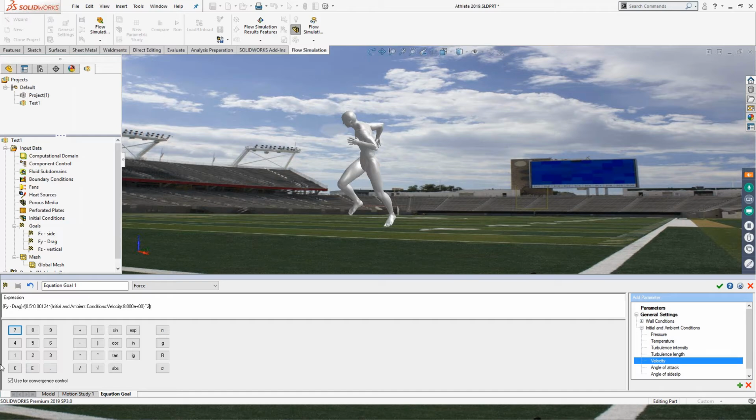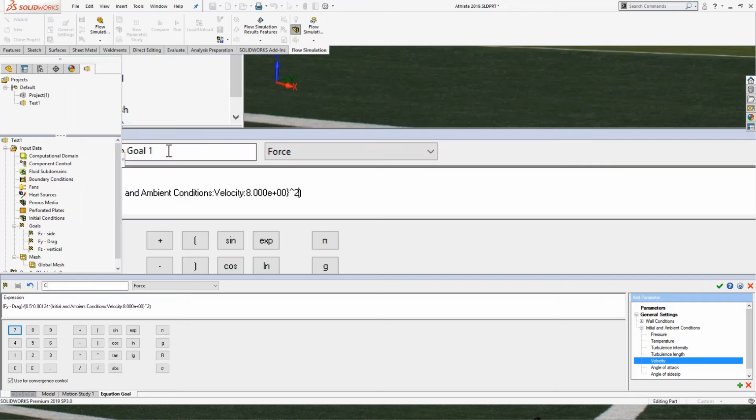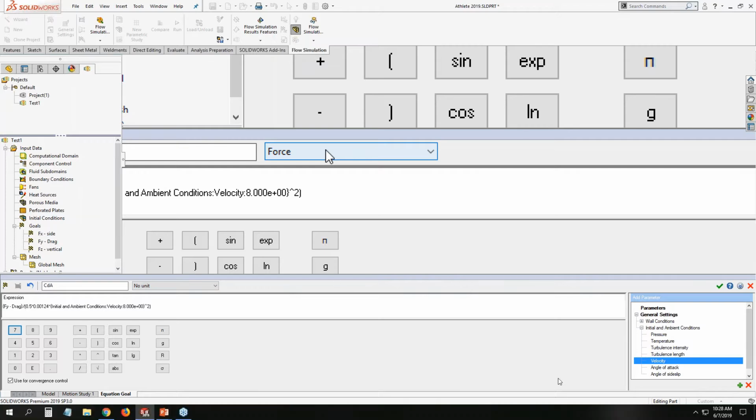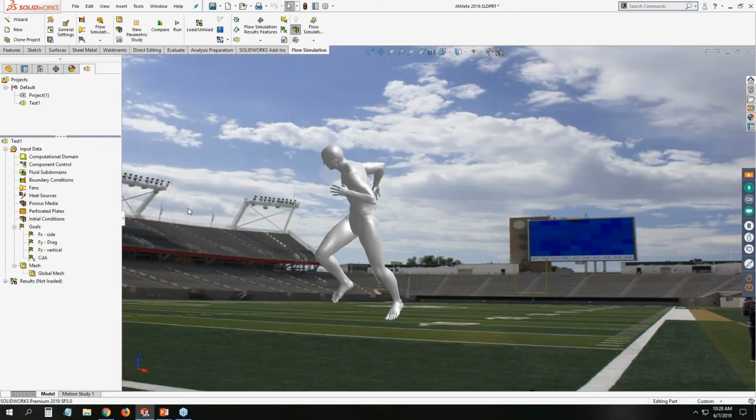Now, in truth, the unit is in yards per second, so I would probably want to define some. That's one of the things, if you want to make sure everything is consistent in the units, that it all works out, they all cancel out, because this unit is actually non-dimensional. By clicking N, I can change that to no unit, and clicking on OK and run that.